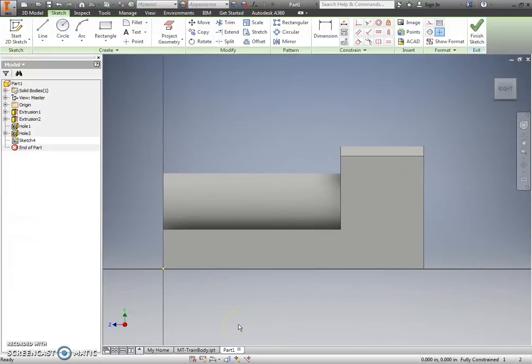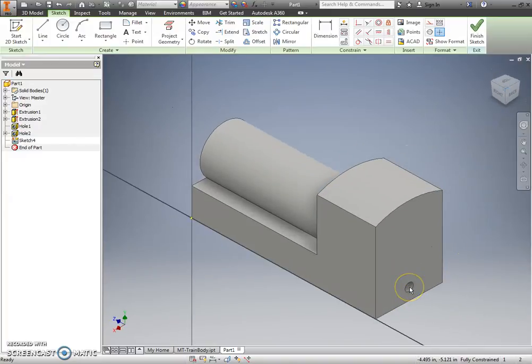Again, if you remember back to the hole videos we covered, I would prefer that you create a sketch, place points, fully constrain those points, and that way your holes are 100% correct, than to try to do it the way that I did this hole by just using your pick and place locations through the hole feature. So I'm going to place my 2 points.